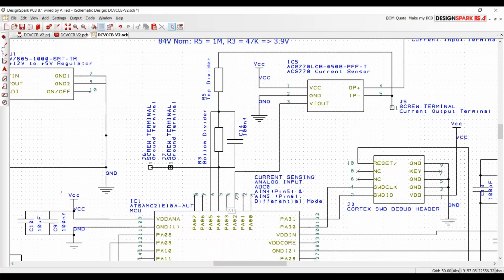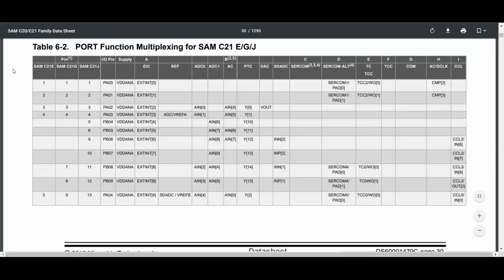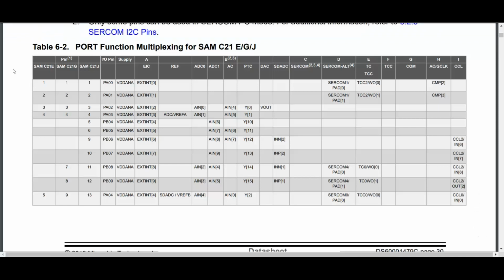It's not working because both of these pins, all of this group of pins, are mapped to the analog to digital converter number 0. Okay, so let's come over here into the chip definition and see how this all lays out. Now, we're looking at the analog input 0 pin of ADC 0.